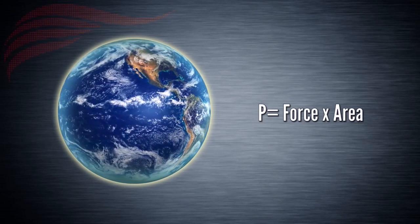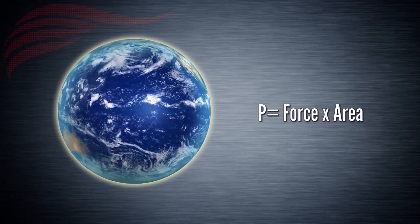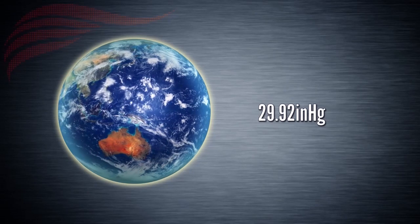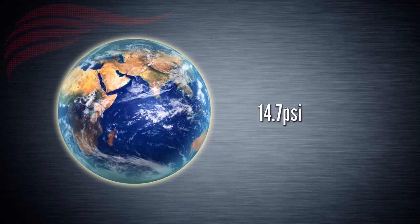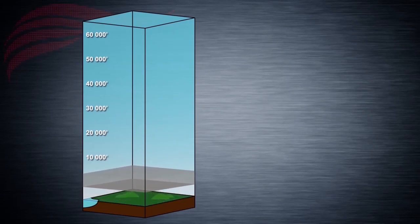Under International Standard Atmosphere, or ISA conditions, air pressure at sea level is measured with a barometer and is either 29.92 inches of mercury, 1,013.25 hectopascals, or 14.7 psi. As we depart sea level and start climbing, the amount of air per unit volume becomes thinner. Therefore, the air density becomes lesser. With this, the air pressure also becomes progressively lesser.